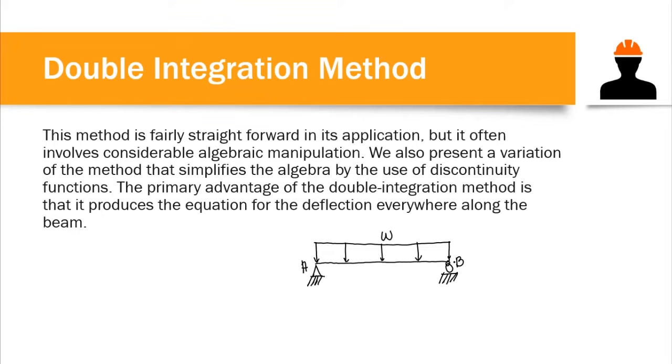Now, if we have this transverse load acting, we also have a deflection in our beam, and that would give us this deflection diagram. I'm drawing it exaggeratedly. This deflection diagram is just a graph of Y as a function of X, in which X is the distance from any specific point in our beam.